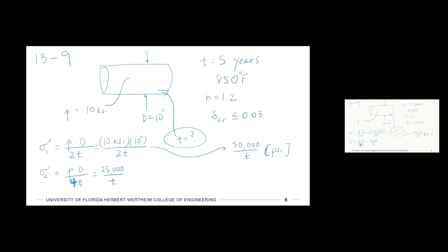Okay. And these are the principal stress directions, if we assume that this is a thin-walled pressure vessel and there's no strain in the radial direction, like compressing the wall thickness, but rather there's plane stress going around in two dimensions. So that means that these directions also correspond to the principal strains, right? So there will be a strain along sigma 1 and sigma 2, right, corresponding to this, or sigma 1 and sigma 3 or something like that, right?